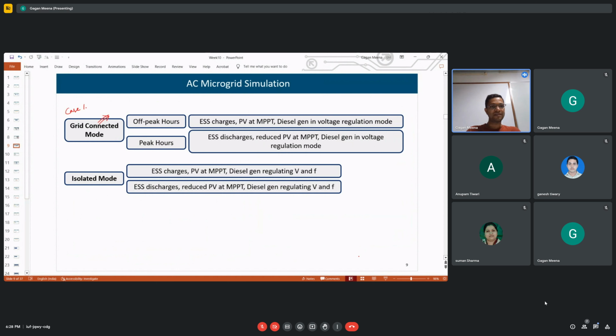Why do we need bidirectional flow, or why does this dual active bridge converter have to be bidirectional? This we have discussed. Can you tell? Because of the power flow from one grid to another grid, load sharing. Yes, correct. So there can be cases when generation is more here and load is less here, and vice versa. So generation can be more on either side, and they can share between them. Power flow on both sides is possible, so that the goal is to supply the entire load. So we can take power from either side.